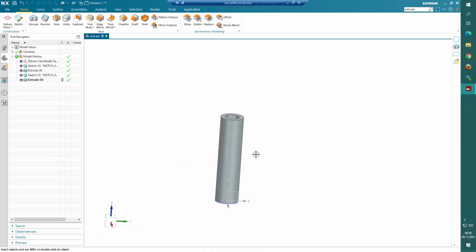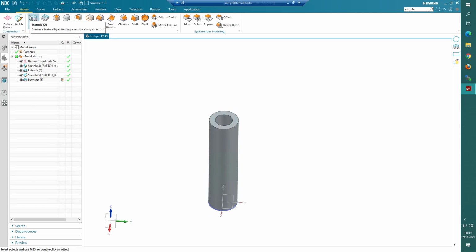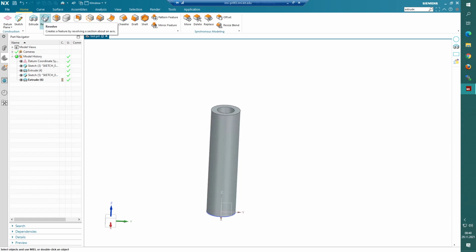The last thing we have to do is make our tip up here, which is this cone. And with the extrude function that we have used so far, you will quickly find out, if you try to do it, that it's not possible to do this cone. For that we need something else, which is the revolve function, the second one that we are frequently using in this course.